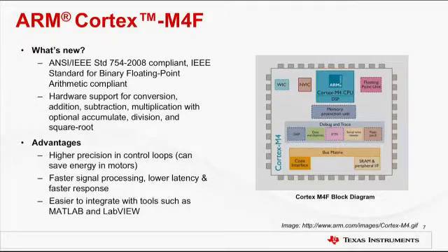The Cortex M4F floating point instruction set does not support all operations defined in the IEEE 754/2008 standard. Unsupported operations include, but are not limited to, the following: remainder, round floating point number to integer valued floating point number, binary to decimal conversion, decimal to binary conversion, and direct comparison of single precision and double precision values. The Cortex M4 floating point unit supports fused MAC operations as described in the IEEE standard. For complete implementation of the IEEE 754/2008 standard, floating point functionality must be augmented with library functions.